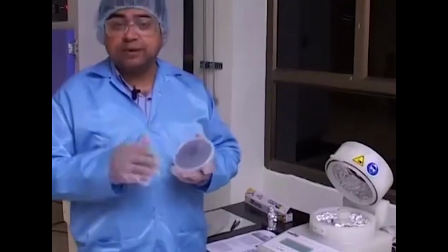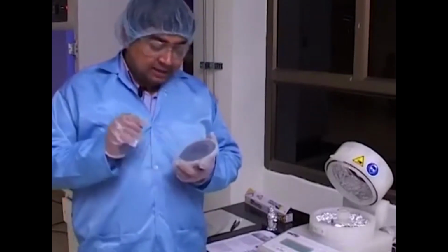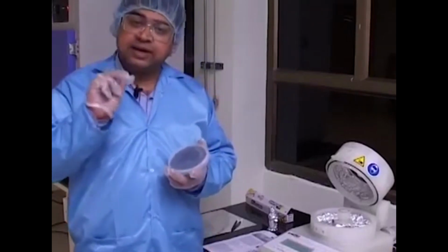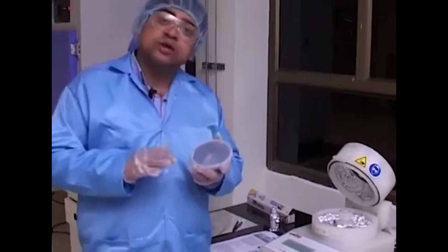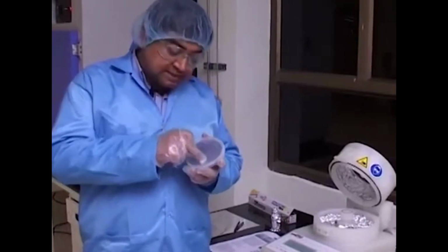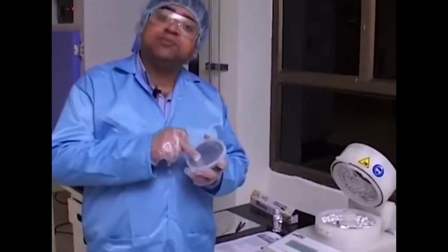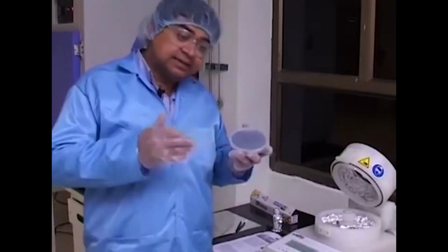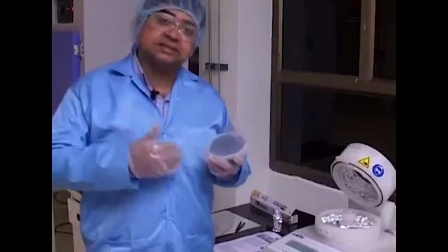This is a circular wafer of about 4 inches diameter, and the goal here is really that the resist should not have any gaps or any islands on the surface as you are spin coating it. So you have to ascertain how much area you need to initially pour or cover so that you have enough resist, so that essentially the spinning process is nothing but centrifugation.